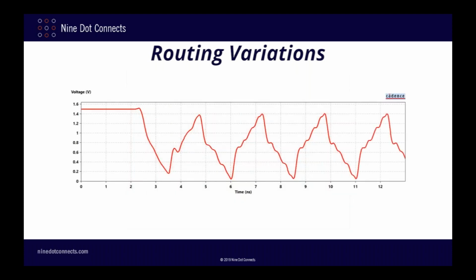And here are the simulation results. I once again surprised myself when I looked at these results because I only saw 1 waveform even though there should have been 4. As it turns out, my layout was so exact that all 4 waveforms overlapped exactly. This was a great demonstration of the main reason for using T-branch topology. All of the branches are of about the same length, and thus all of the signals arrive at the DDR3 chips at about the same time.